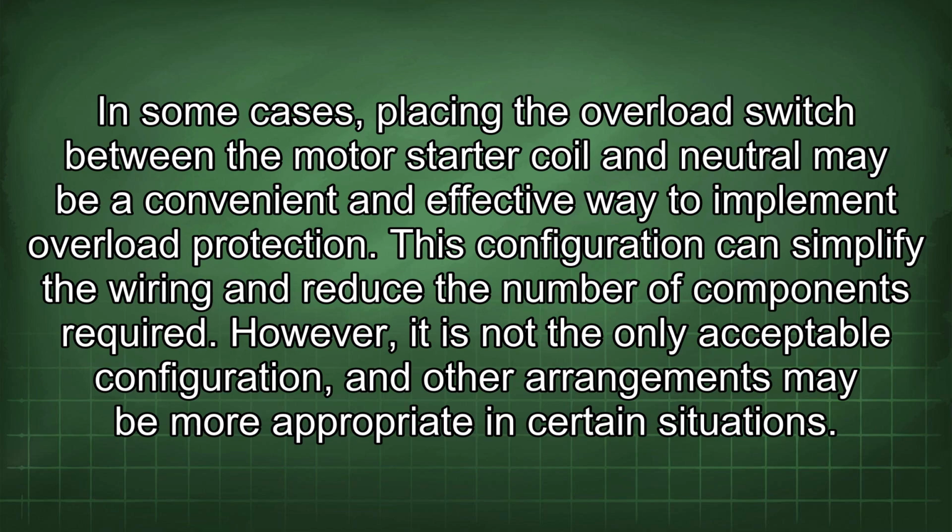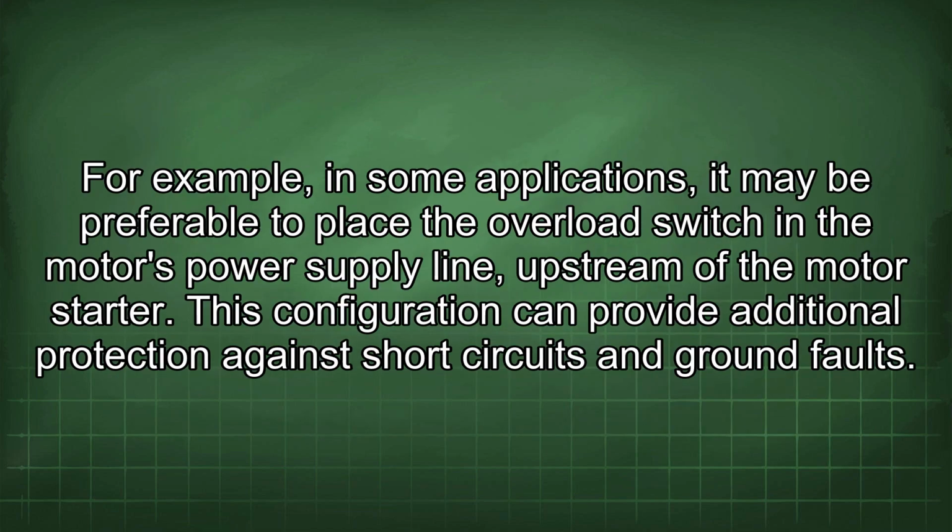However, it is not the only acceptable configuration, and other arrangements may be more appropriate in certain situations. For example, in some applications, it may be preferable to place the overload switch in the motor's power supply line upstream of the motor starter. This configuration can provide additional protection against short circuits and ground faults.